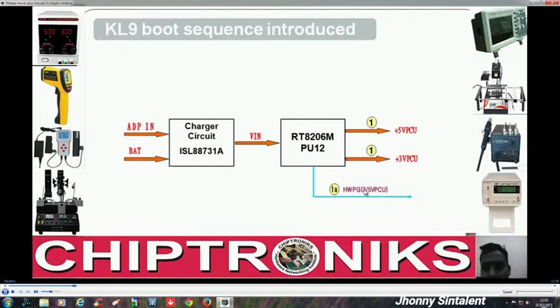I'll just mention briefly over here that all the power good will eventually go to PCH, because PCH and embedded controller, that is the IO controller, they are at the core of power management. But here this is the 3.35 volt regulator IC, so this power good will go first to the IO controller, right? They'll all bunch together. Every regulator IC will generate a power good, and all those power good will be combined together and go to the IO controller, right?